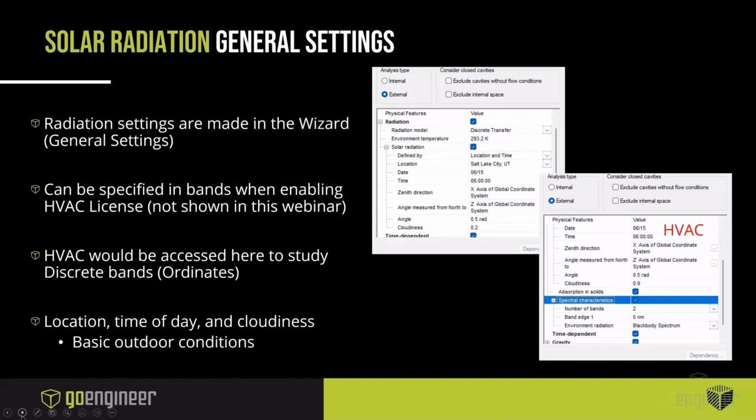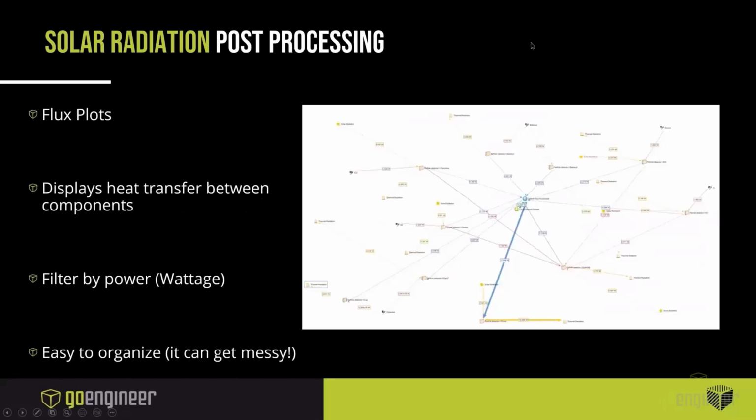And I'll also show this later, so if you're confused, this will make sense a little bit once I show everything. So the really cool thing that I like about the flow simulation study, and what I was actually looking for, is the flux plot. The flux plot tells us how much heat is being exchanged between one component and the next and where that heat is coming from. I know this is a very undetailed picture. There's a lot on here, and this was the best I could do for what SOLIDWORKS is giving us. There are better ways to pull this data. I'll show you how we do that later, but we can also pull this as a PNG file, so you don't have to open SOLIDWORKS every time you want to look at this data.